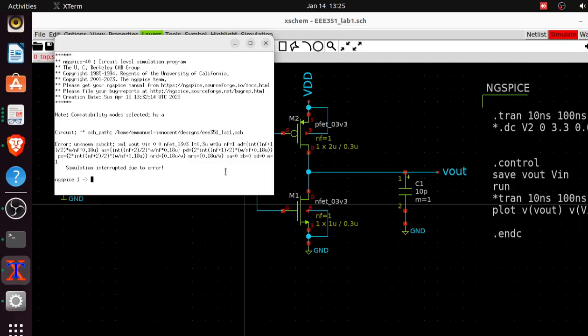So what's the problem? This is an object, remember, all these are objects, so it can't recognize it, and it's only that object, this transistor object, it can't recognize. That's because this is a schematic. A schematic is different from ngSpice, and ngSpice is different from the PDK you're using. So these are different party objects working together. A schematic just helps you get this together, so from a schematic, you picked this component that belongs to the PDK you want to fabricate with.